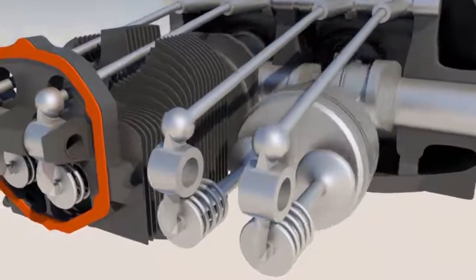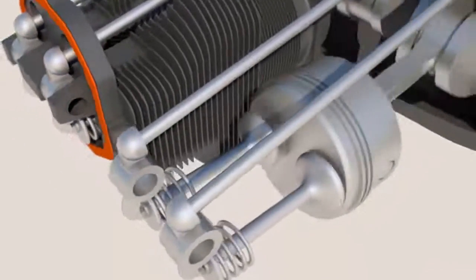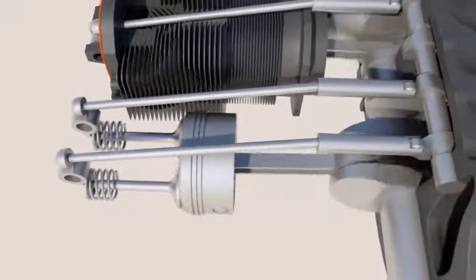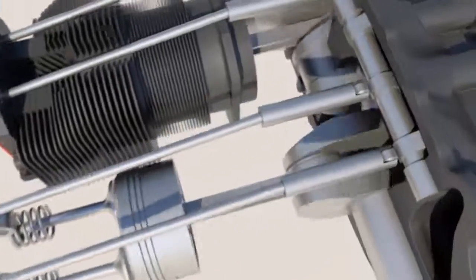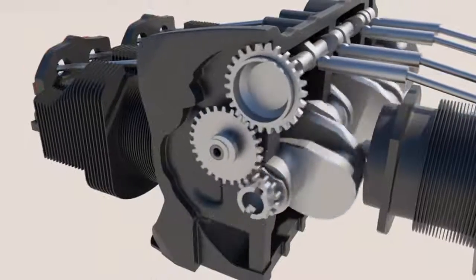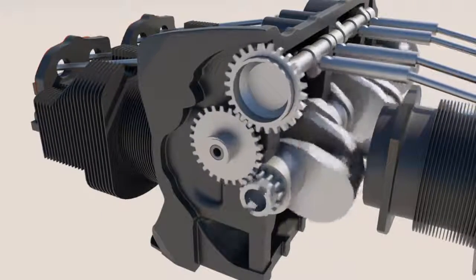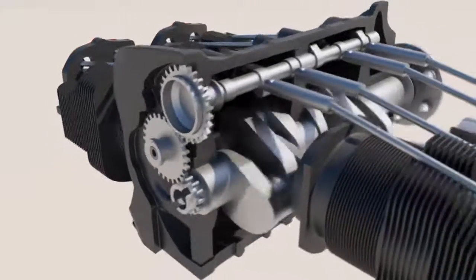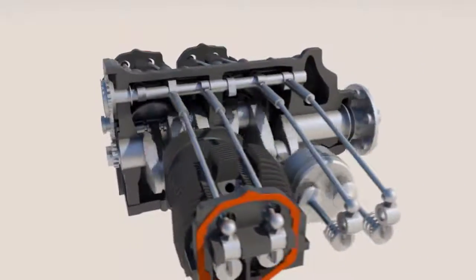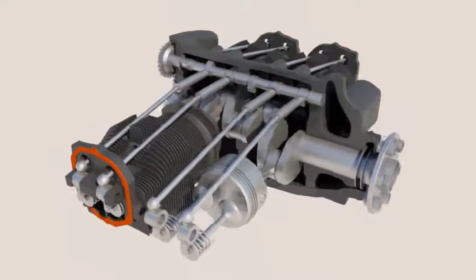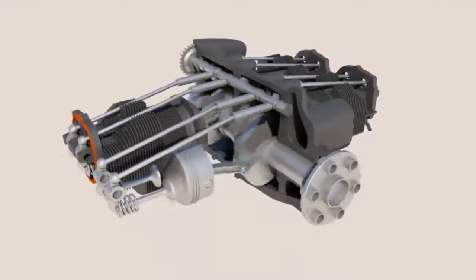The valves are spring-loaded and will return to the closed position as the camshaft lobes move away from their respective rod. Getting the valves to open at the exact moment is very crucial for the engine to operate. Because of that, the camshaft is geared to the crankshaft so they will remain synchronized. The camshaft is geared to spin half as fast as the crankshaft. This results in the valves opening twice during the four-stroke cycle.